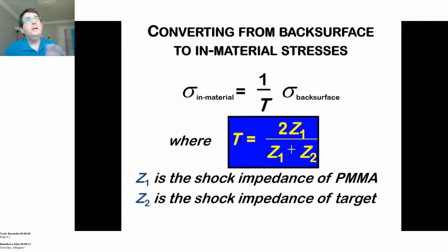By using two gauges in the system, we can also measure the time between those two gauges, knowing the thickness of the epoxy and the sound speed in the epoxies. And you can adjust those velocities depending on the stress you're getting to. So basically, you're using two gauges to give you extra information which you can compare between those two diagnostics.